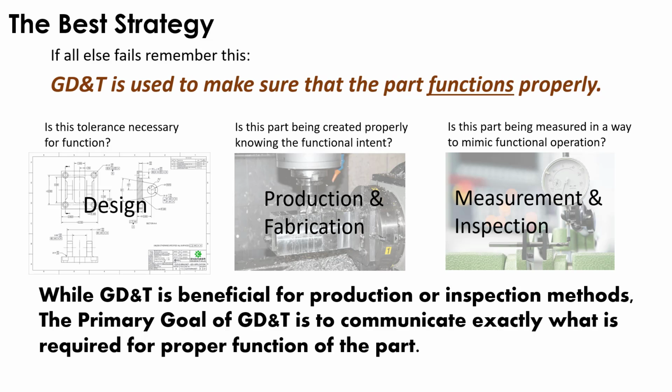Engineers definitely get scared on a coordinate dimension print about how you actually do that and not have something that's just terrible looking. Well, with GD&T, we can do it because we're zeroing in on here's the datums, and then here are all the features, whether it's a surface feature or a feature of size, and then we're using geometric controls, and not always, to relate that back to the datum reference frame if that's what's functionally required.